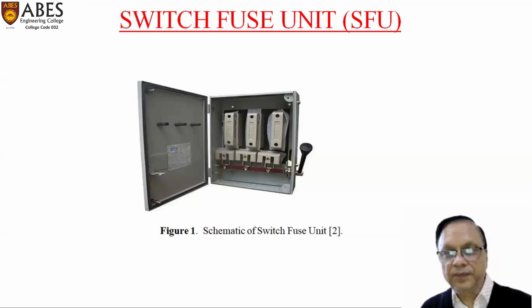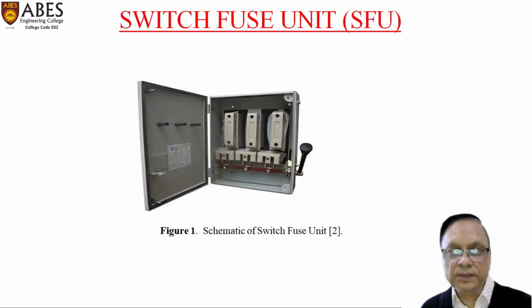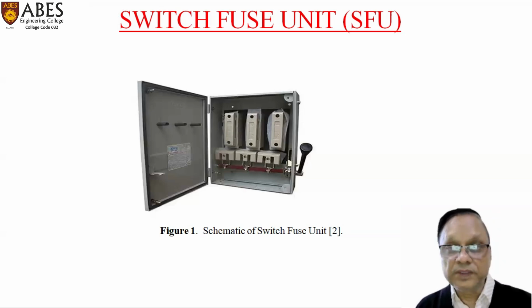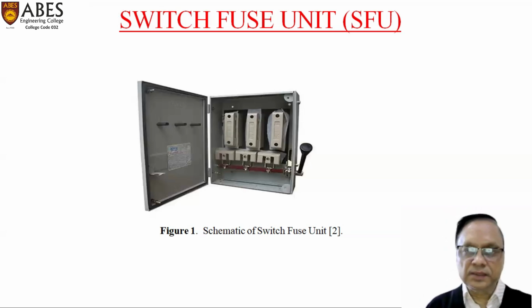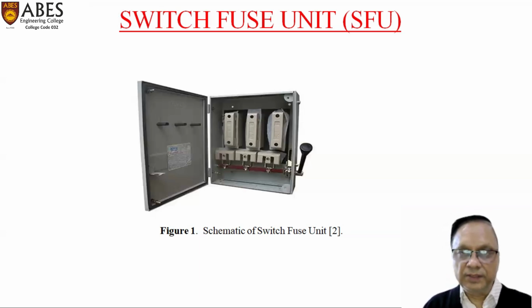Normally, what happens is that we don't get the wire, the size of the wire, the current rating of the wire which is being used. So under this condition, sometimes we replace it with either an oversized wire or an undersized wire, due to which again the system will become faulty, because under overload condition again the fuse will get fused. Normally, we should have the same rating of wire with the same gauge wire size which was used in the original manufacturing.